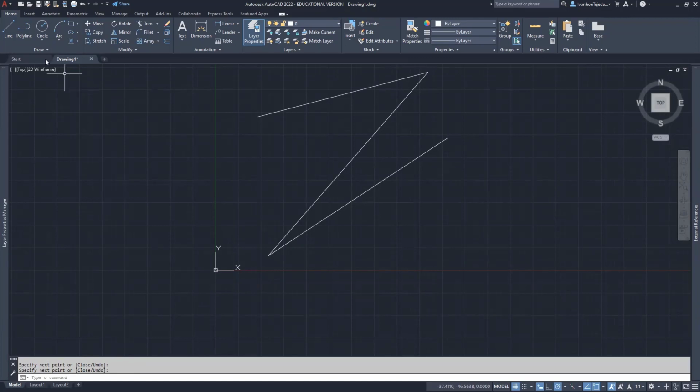And the reason for that is because when I go to pick a command, for example, let's say circle, it appears at the top of the command line here. And then at the bottom, it says, okay, what do you want to do? Draw a circle, specify the center point. Okay, center point is right here. And then it continues, but you'll notice that it keeps adding to that running tab, right? So I can't stress it enough. Let me tap the escape key because I don't want to do a circle now. I can't stress enough how important this command line is. Do not close it. If you close it, I have to show you how to open that back up, but we're good.